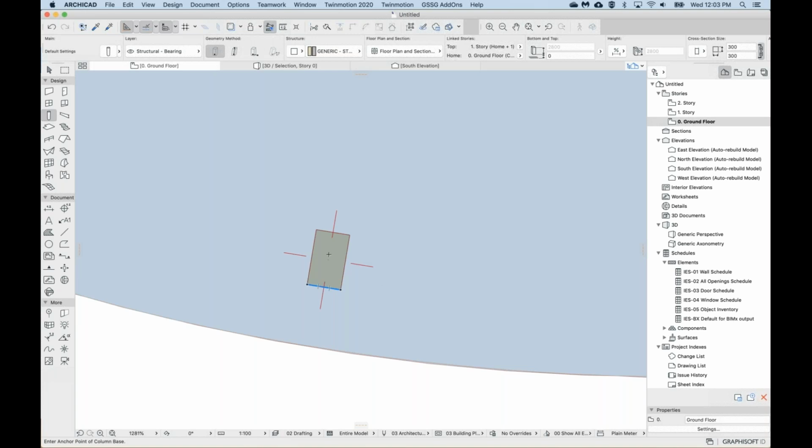Okay, so selecting the column to rotate again. We're using Control E, using the center point. And if it's vertical, then we use the Y axis. So click for the Y axis, and then I'm moving my cursor to rotate it. Then I'm hovering my cursor over the edge of my shell, and it will show me a pencil with a line in the center of it.